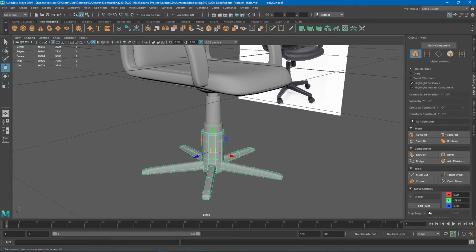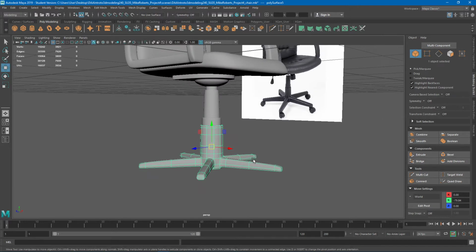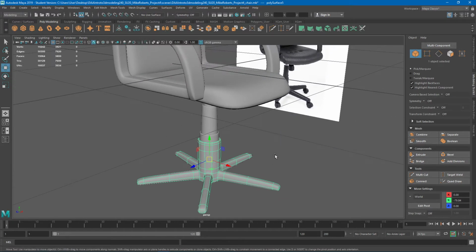3D Studio Max is about the same, but just about all packages give you some ability to reorient their manipulators or reposition their manipulators. So you're always going to be in a solid position for that stuff. Even though you might find some extra little cool tricks in other software, like, oh, that's neat, right? But the basics are the same on all the software, right? And this just gives you that ability to pick different orientations for your manipulator. And we're not trying to be exhaustive about all of these. Some of these are highly specific, super useful in very rare circumstances. The ones that you'll probably use the most will be things like world, object, component, or custom, which is just your edit pivot.